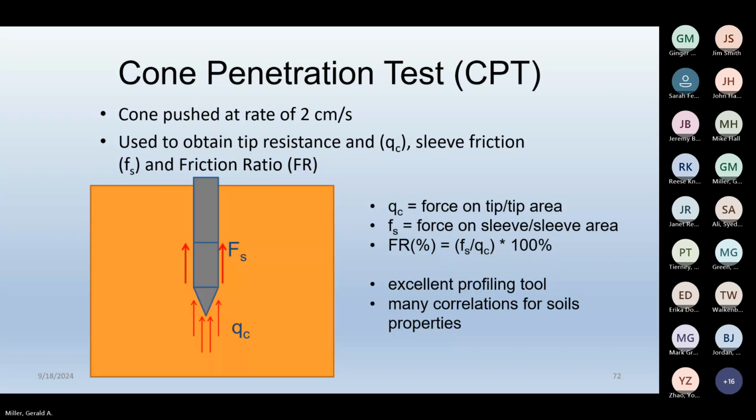So I'm not saying it's not worthwhile. I'm just saying be careful in how you interpret pore pressure measurements in an unsaturated profile. I still think there's some use to having it part of your exploration. When you hit the water table, you often will see it pick up and you can detect where the water table is. But just be aware of that.